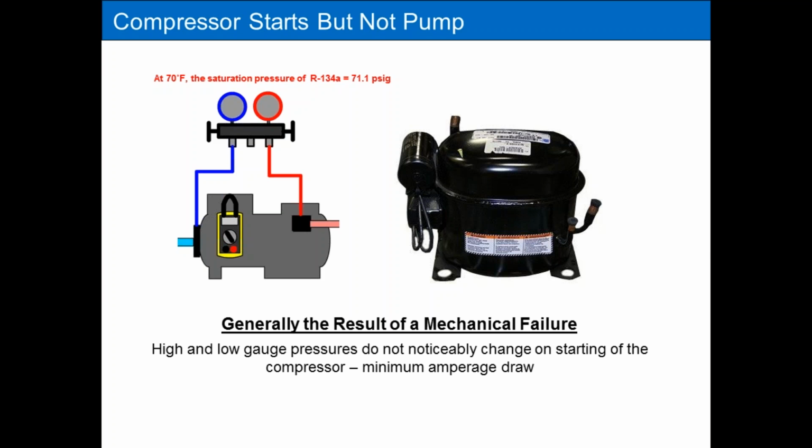If your pressures don't change, you start it up, measuring current, it's drawing current, compressor's running, but the pressures don't change or they change very little, you've got a bad pump and a leak. You've got two scenarios going on, and that is not uncommon. It is something that you may find where a loss of refrigerant caused the compressor to fail, and you've got two things to deal with.